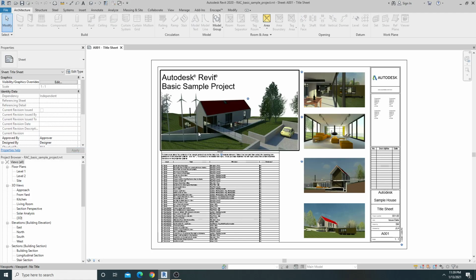Okay, before we begin, really important, if you were to download Revit software from the Autodesk website, you need to make sure that you download the Autodesk Revit 2020 version and not 2021 or 2019. The reason being, Autodesk Revit is one of the few software that has no backwards compatibility, which means that if you open or save a file in 2021, you can no longer work on that file in 2020 or 2019.